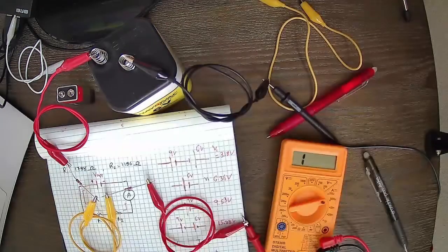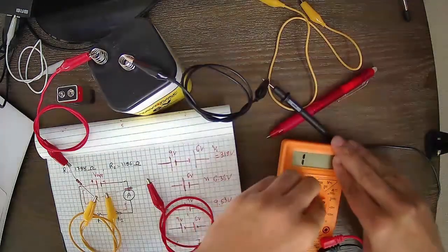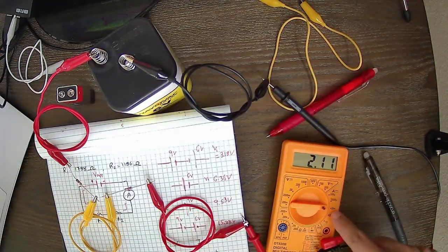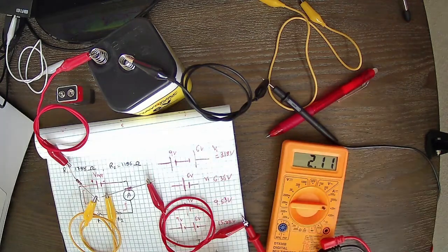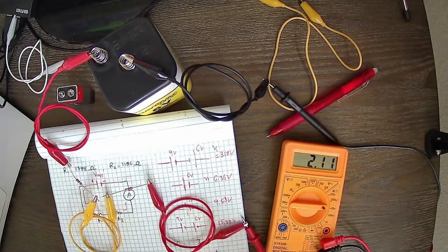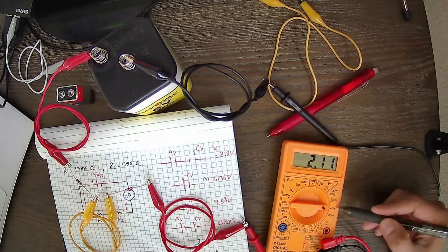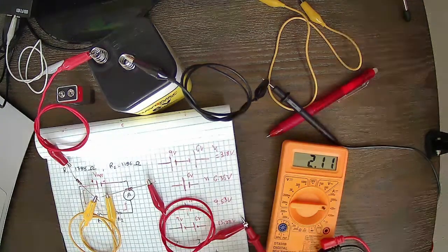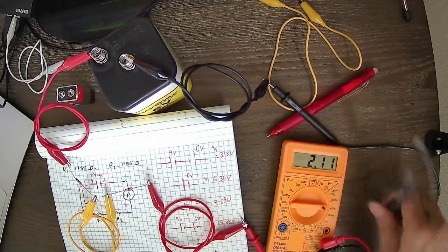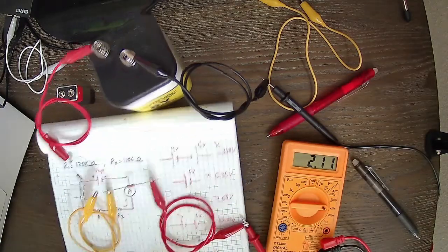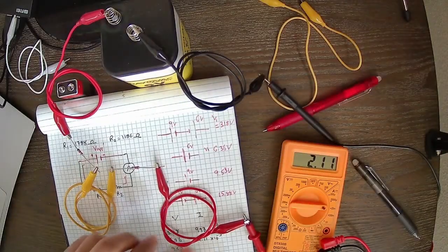Alright, so it's gone beyond 2000. Now it's 2.11 milli, so 2.11 times 10 to the negative 3. That's the current. Remember, again, just pay attention to these little symbols here, the prefixes, the mu and m. Mu is 10 to the negative 6 and m is 10 to the negative 3. So we got it now for the 6.36 volts.